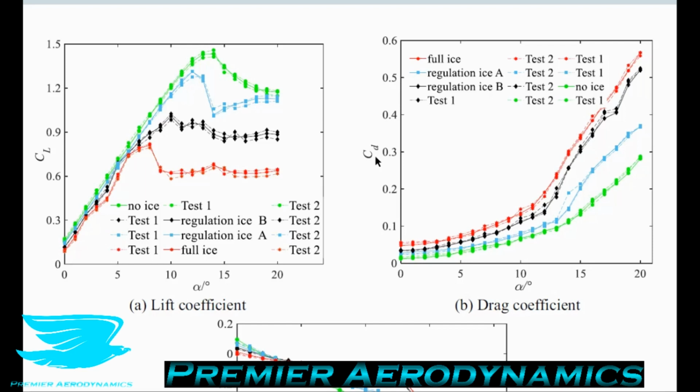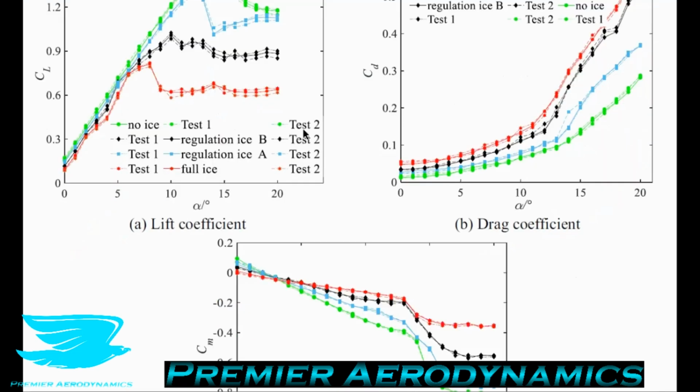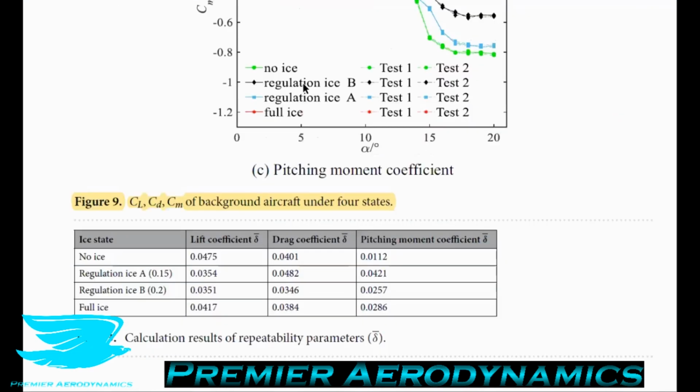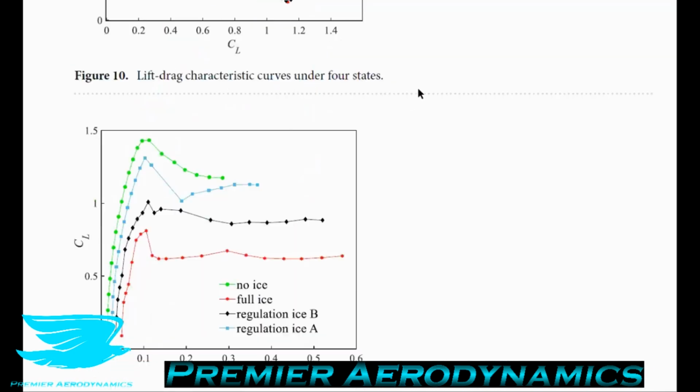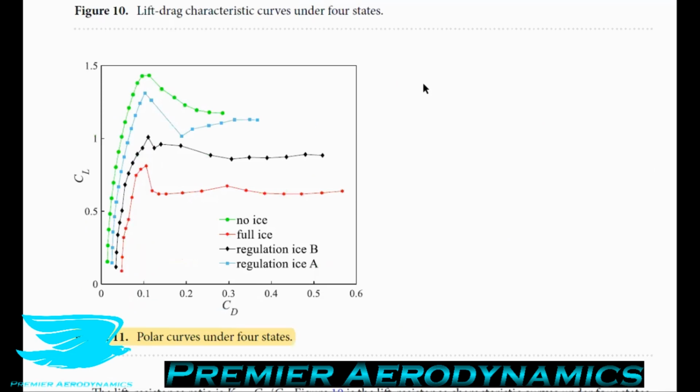And this is what we're seeing here when we put ice onto the leading edge. If you put a bit more ice on the leading edge compared to none, then you'll get a gradual reduction in the lift coefficient. So the stall has been tempered a little bit, which is very reminiscent of tubercles again. So this shows me again that tubercles are very closely related to this geometry, and that makes sense to me. So we can conclude that any ice is bad for low angle of attack aerodynamics, but during the stall stage, you can argue that having some ice is actually good.